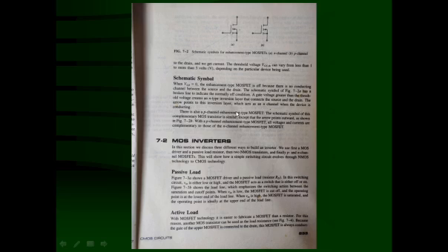There is also a P-channel enhancement type MOSFET. The schematic symbol of this complementary MOS transistor is similar, except that the arrow points outward, as shown in figure 7.2a. With a P-channel enhancement type MOSFET, all voltages and currents are complementary to those of N-channel enhancement type MOSFETs.